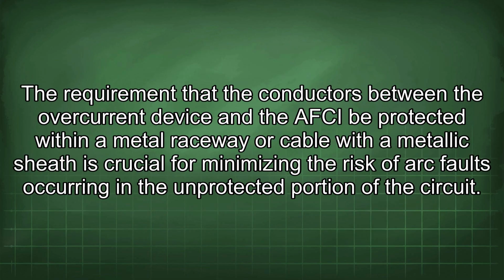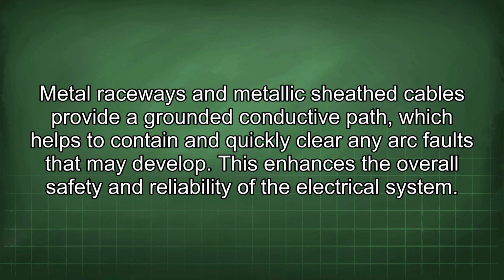The requirement that the conductors between the overcurrent device and the AFCI be protected within a metal raceway or cable with a metallic sheath is crucial for minimizing the risk of arc faults occurring in the unprotected portion of the circuit. Metal raceways and metallic sheathed cables provide a grounded conductive path, which helps to contain and quickly clear any arc faults that may develop. This enhances the overall safety and reliability of the electrical system.